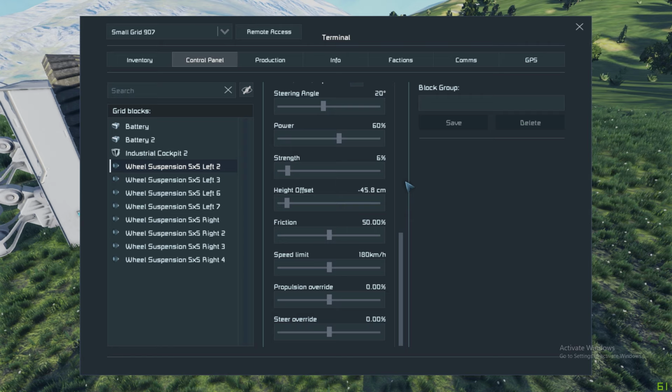The default is 20%, and that's pretty fine for most generic rover needs. If you have a very fast rover, you might want to consider dropping this down to 15% or so. This will help you prevent flipping over when you turn. You must remember the steeper this angle and how fast you're going may result in your rover flipping.